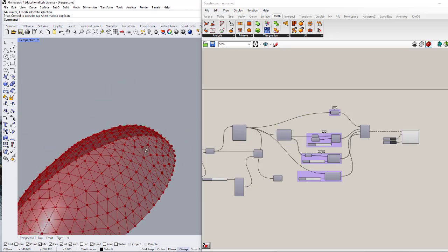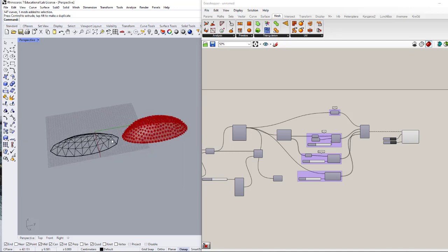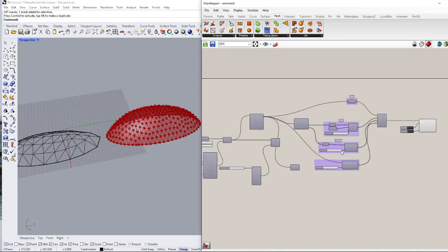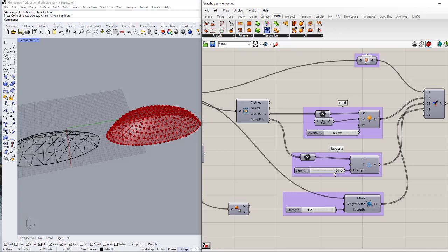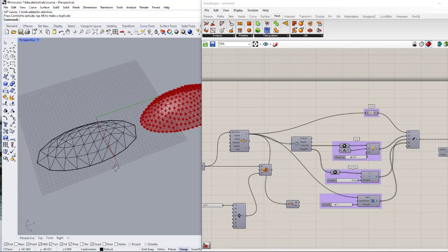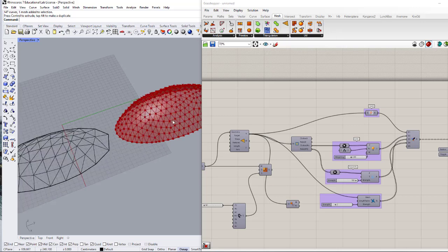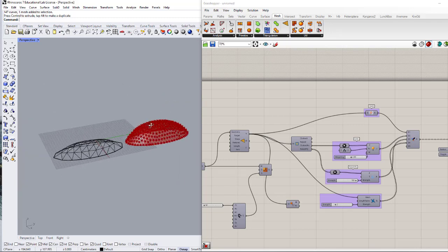So this is much more smooth than what we had in the first mesh. And also, as you see, the deformation with the same numbers for the load, for the strengths of our anchors, and for the strengths of our mesh edge lengths, this is more deformed than this another mesh. Both of them are triangular, but the edge lengths for each triangle in here are similar to the others, but in here they're different.